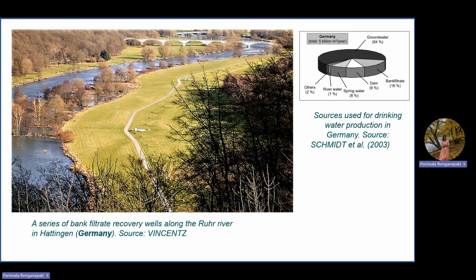This is one of the managed aquifer recharge structures, river bank filtration. Because when we put the well near the river, the contribution from the surface water to the ground will be very high. When we pump, a larger amount of water with high pressure will be reaching the pumping well. So indirectly we are recharging from the surface water of the river.